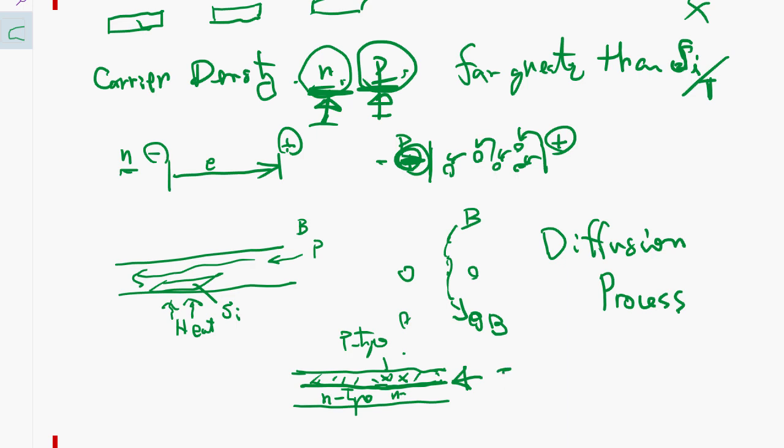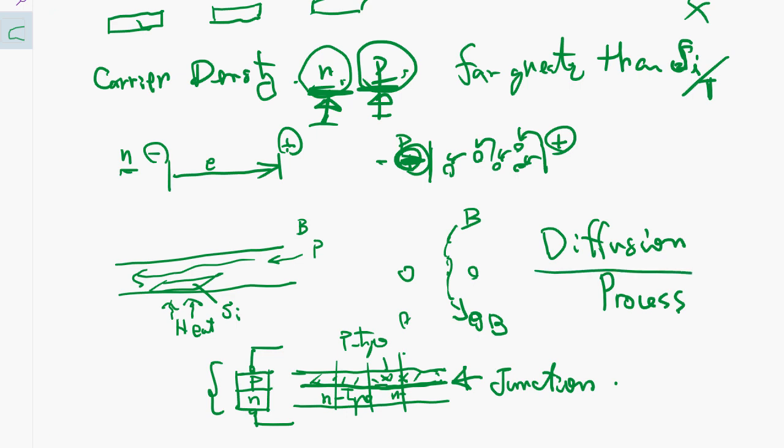So we call that the junction. And in this case, we slice this silicon, make one piece of diode. It's a P and N, and we put the lead. So that's the way we make a diode. And transistor, we talk about this in detail later. It's MOS and bipolar, the basic method of diffusion.